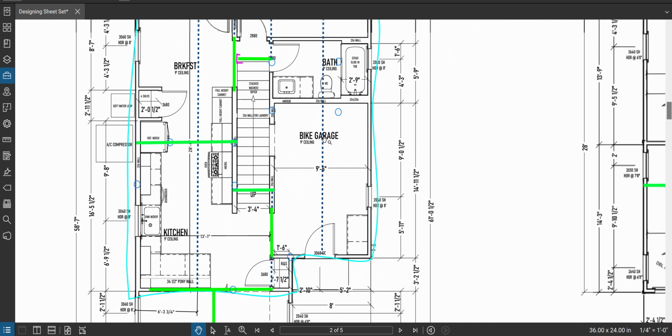Now notice here what's happening. Sometimes things come down on door headers. So we happen to know that that's a particularly special door header, and we need to design this door header. We need to keep this in mind and design this guy. We will also now need to design this guy because we have a special load coming down. We can't use average numbers and things like that.